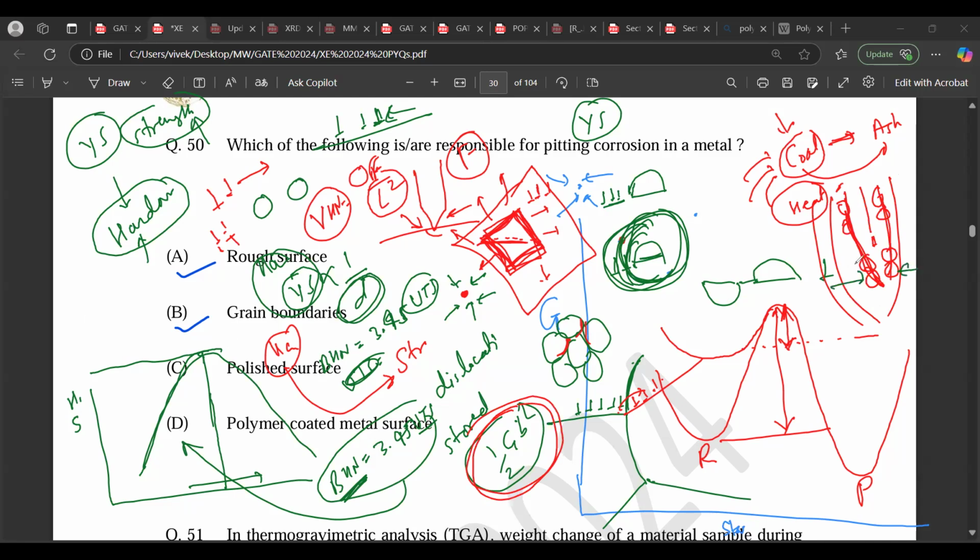So naturally, currently they are forced to move inward, which means they naturally want to go outward. That means here it is a tensile strain. And here they are forced to go inward, but they want to go outside. That's a tensile, and here is a compressive strain. So there is a strain associated with each dislocation, and that strain is carrying stored energy.